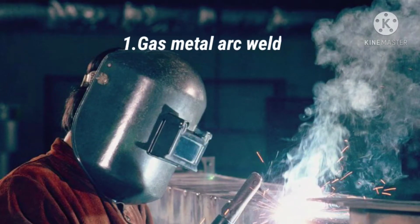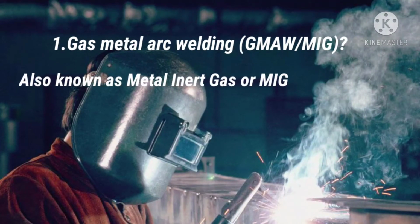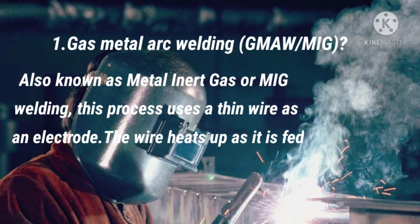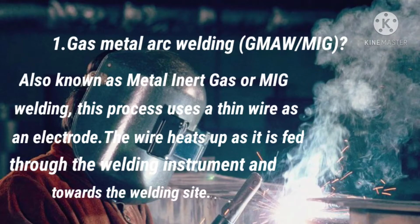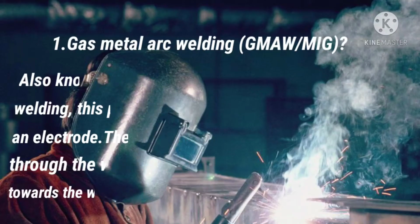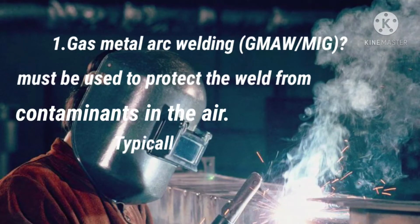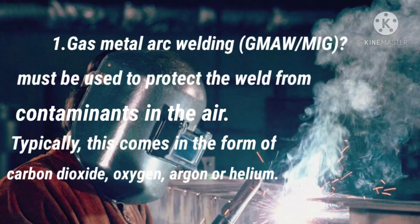Gas metal arc welding, GMAW, MIG. Also known as metal inert gas or MIG welding, this process uses a thin wire as an electrode. The wire heats up as it is fed through the welding instrument then towards the welding site. Shielding gas must be used to protect the weld from contaminants in the air. Typically, this comes in the form of carbon dioxide, oxygen, argon, or helium.